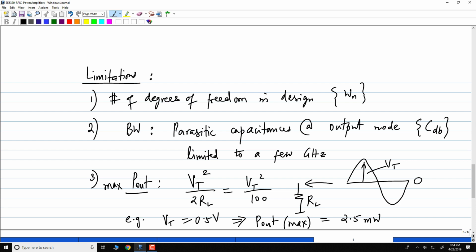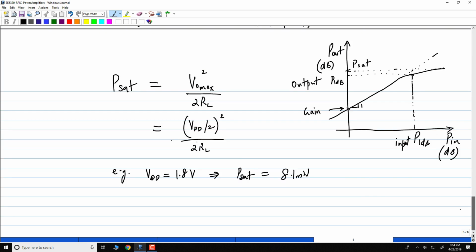There is no information contained in the amplitude of the signal. If that is the case, you can very well operate in this region, no problem at all. Linearity is needed when the amplifier is linear, whereas here the information is carried in the zero crossings. If that is the case, this doesn't matter so much.